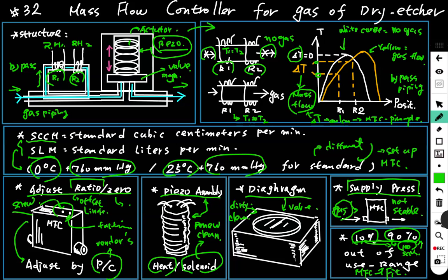There are many kinds of MFC, and they have many kinds of flow range. You can use the suitable flow range MFC to install in your piping. Maybe you use the wrong MFC and it is out of range, or you renew with a wrong MFC, which also causes it.